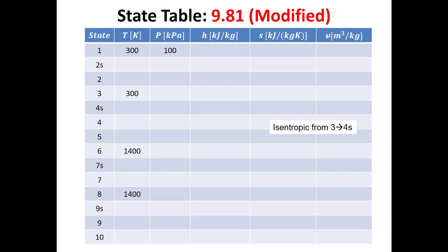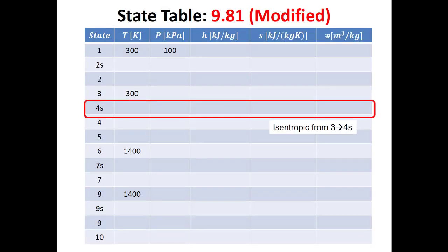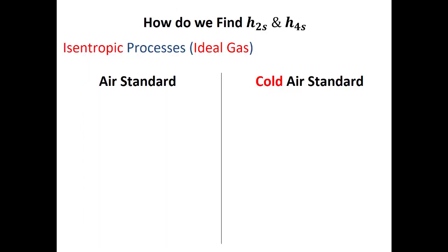Next, I'm going to look at the isentropic process between state 3 and state 4. Now, this is my second compressor, so I ultimately do state 4s and state 4 in the same way that I did state 2s and state 2. So first, I'm going to find the isentropic outlet of this second compressor. I remember that I'm using an ideal gas and I want to use these isentropic relationships. So if it's variable specific heat, I want to find delta H, but I don't know H4s.